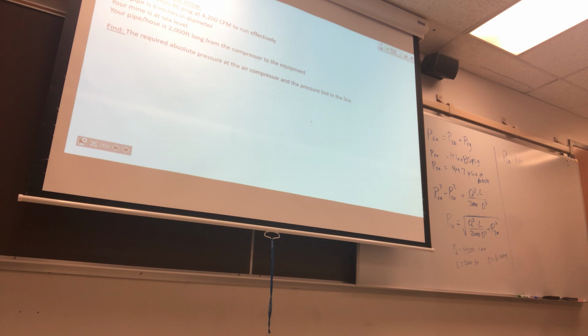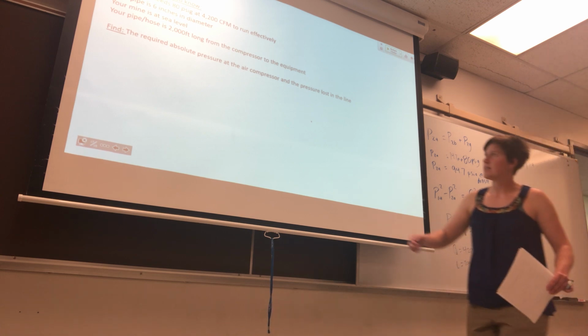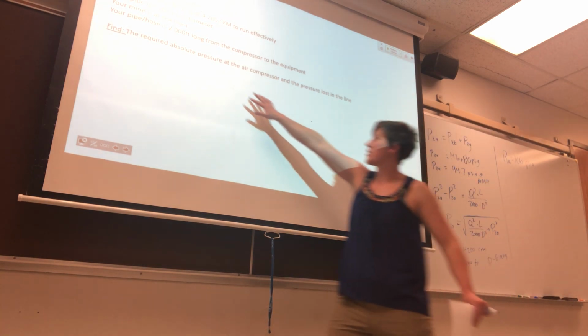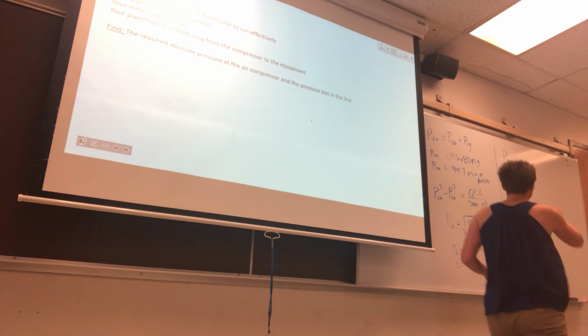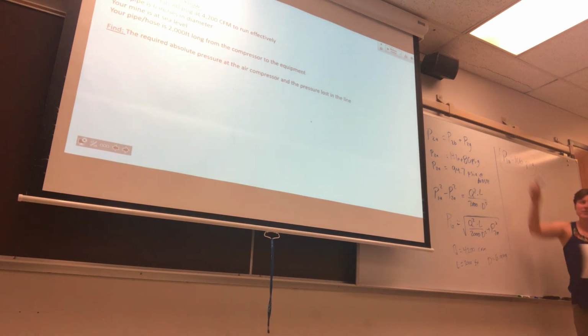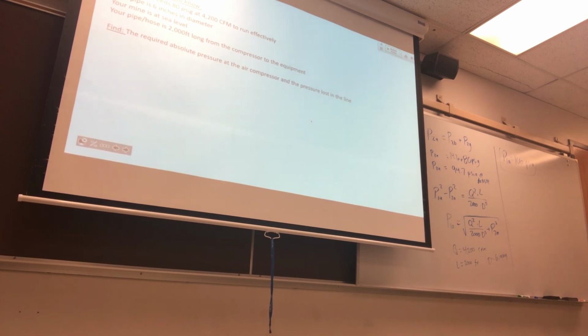What's the units of that? PSI. Cool. We have the absolute pressure at 1, but it's asking us, okay, oh wait, no, it says what's the absolute pressure? Yeah, I guess that's the answer. So that's the absolute pressure, but our gauges are not in absolutes. So how do we change this into now the gauge pressure that we need to read at the compressor? Just subtract 14.7.